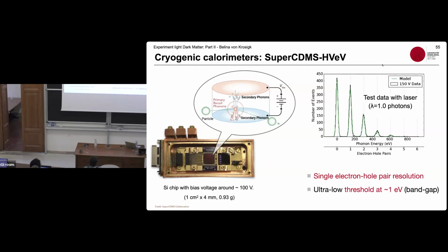That's basically the baseline resolution in the end. So yes, the baseline resolution goes negative, but just because these are really noise fluctuations around the baseline. Particle deposition wouldn't go negative. This is 0 energy deposition plus or minus the baseline resolution. But every so often you're observing 1, 2, 3, 4 electron hole pairs. And a single photon cannot get you more than 1 electron.